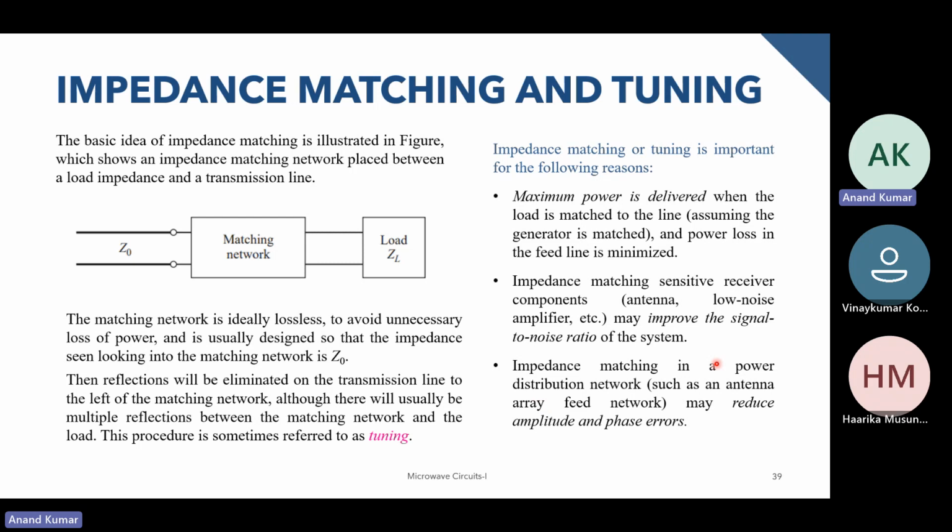You'll have to make sure that the impedances are matched, and over there, these matching networks come into play, because most systems have a 50 ohm output, and your array element can also have 50 ohm as the input impedance. But you cannot split the 50 ohm into 50 ohms. The 50 ohm will be split into, for example, if you have two elements, 25 and 25, something like that. And then again, you cannot feed the 25 ohm to 50 ohm directly.